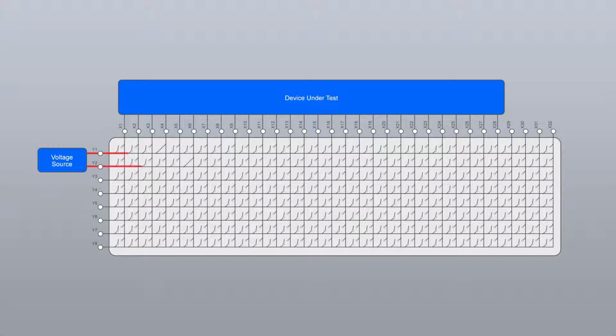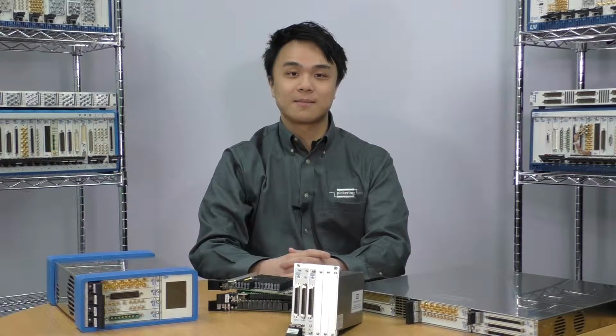A voltage source can be connected to any two terminals of the device under test, as shown, and a programmable resistor is connected between another two terminals. Operation of the device under test can be verified by connecting a voltmeter between yet another two terminals. The device pin connections can easily be reprogrammed, so this system will serve as a generic test system to test a variety of parts.